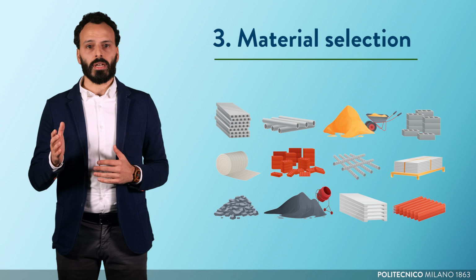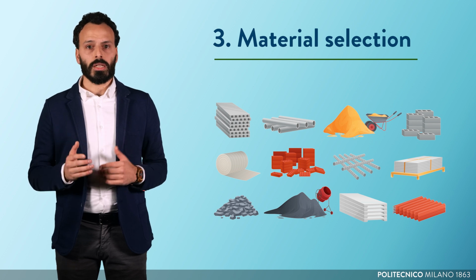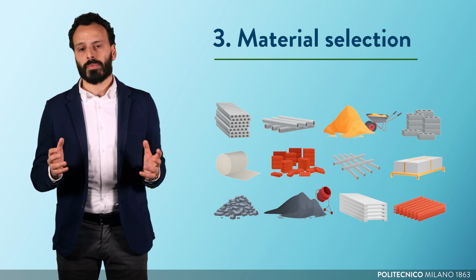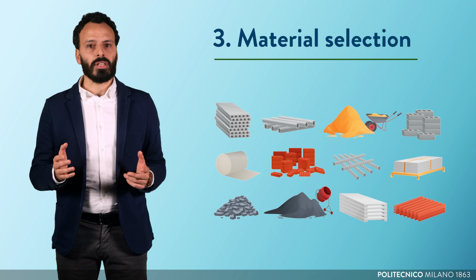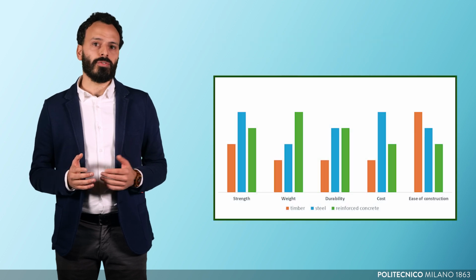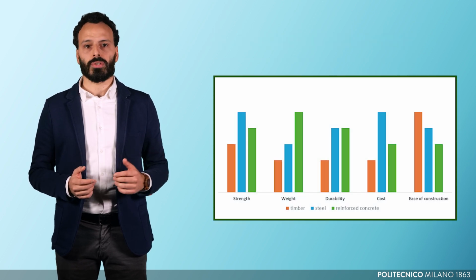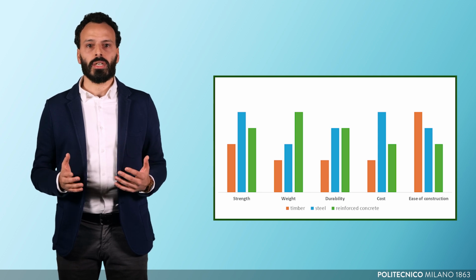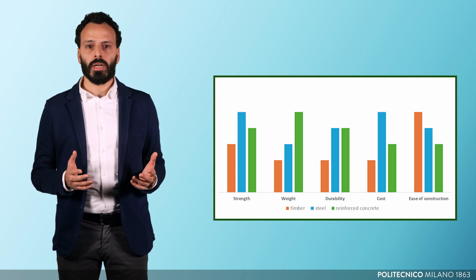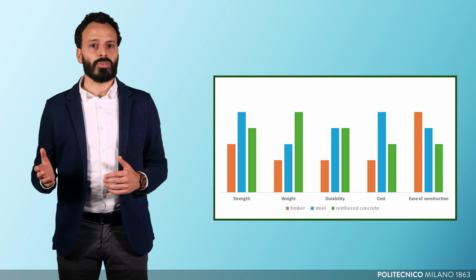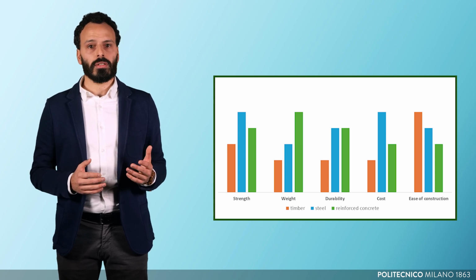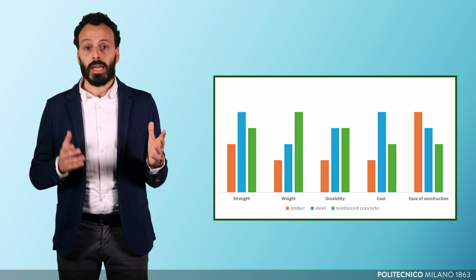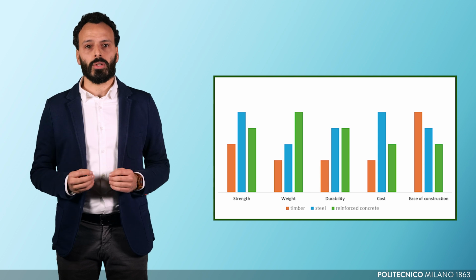Selecting the proper material for small river bridges depends on several key factors. Local materials, like timber and stone, are often the most affordable and accessible options. Durability is another important consideration, especially in environments with high humidity, temperature fluctuation, and seasonal flooding. Moreover, the compatibility between material and static scheme has to be taken into account.